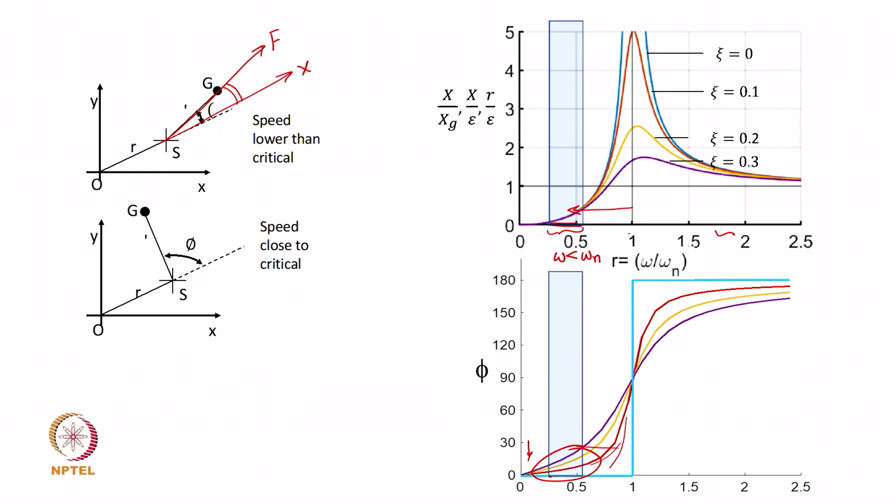That's how it shows up. And so, if your rotor is spinning and whirling, as the shaft center whirls around the bearing axis, the mass center will be located outside of this circle, and the shaft is going to be lying here, and the mass will be flipped outside of that whirl circle.